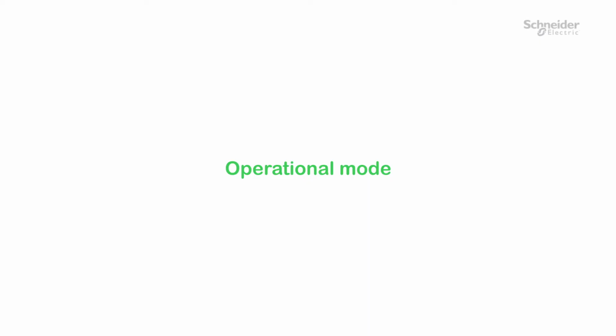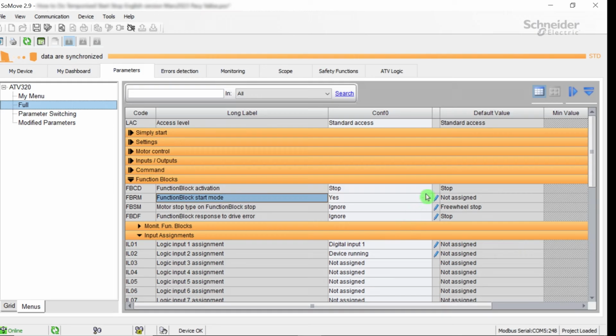Operational mode. The FBCD, FBRM, FBSM and FBDF parameters in the Function Blocks tab manage the running mode of the ATV Logic tasks in parallel of the Drive application task. The Drive application task is running with DI1, hardware logic input, and the motor is running. The ATV Logic tasks and their behaviors in case of errors are managed by these parameters.